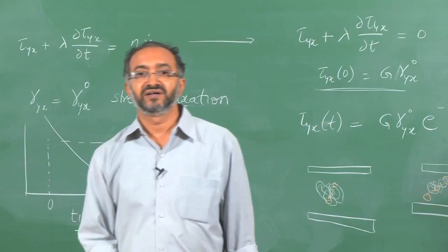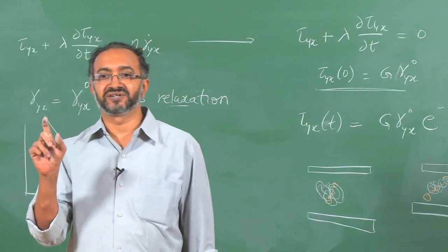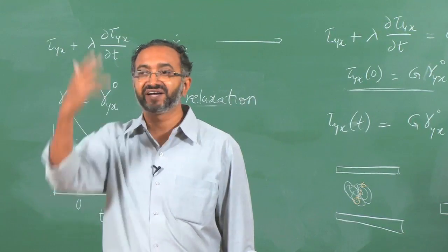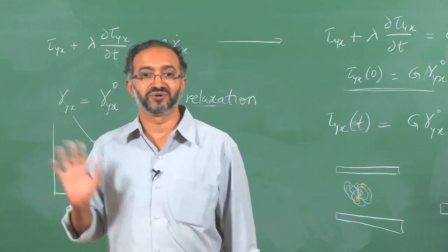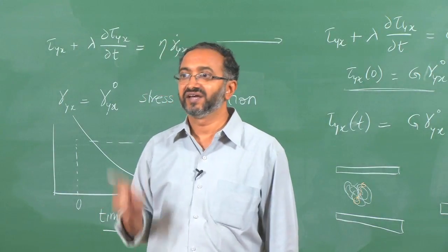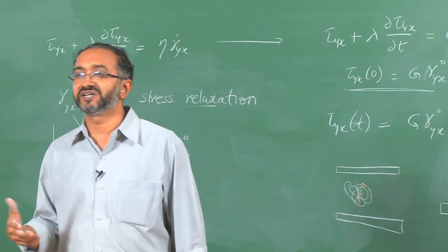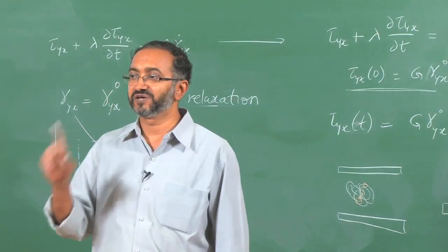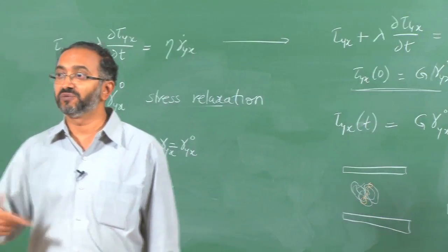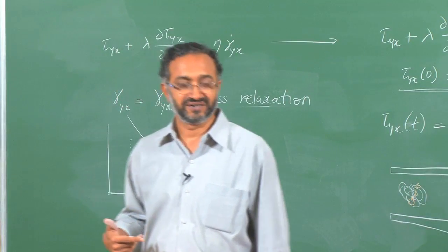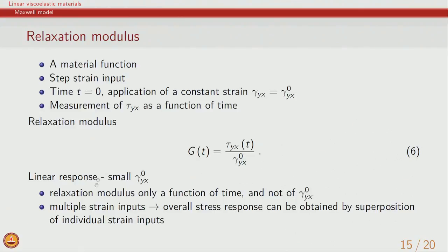In this case, we are not evaluating one constant; the whole curve itself is an indication of the material response. If I get an exponential curve, right away I know this material has one relaxation process, and I can also say what its relaxation time is. But in general, most common materials will not fit one exponential, and it is our job to find out the meaning of the multiple relaxation processes in the material. All of this is also very important in terms of the amount of deformation.